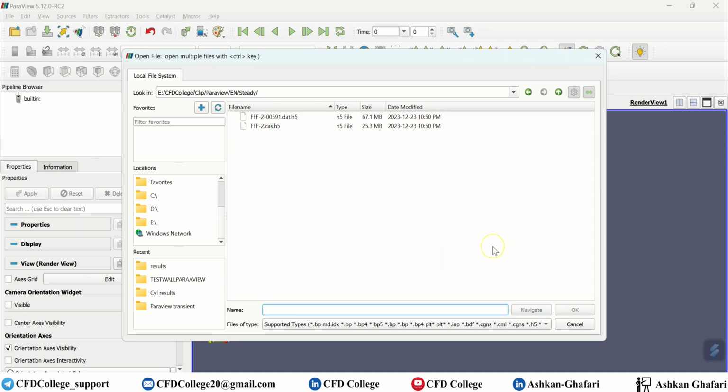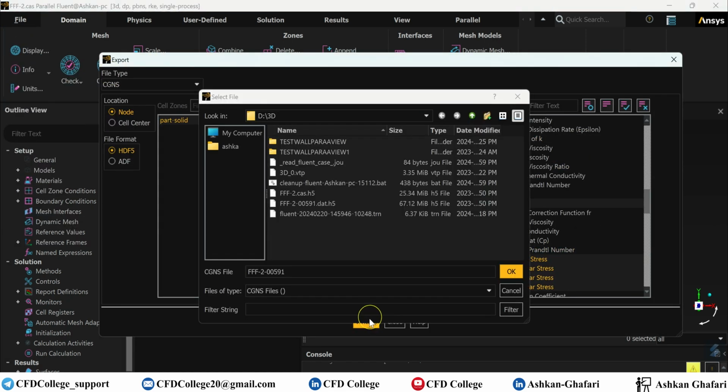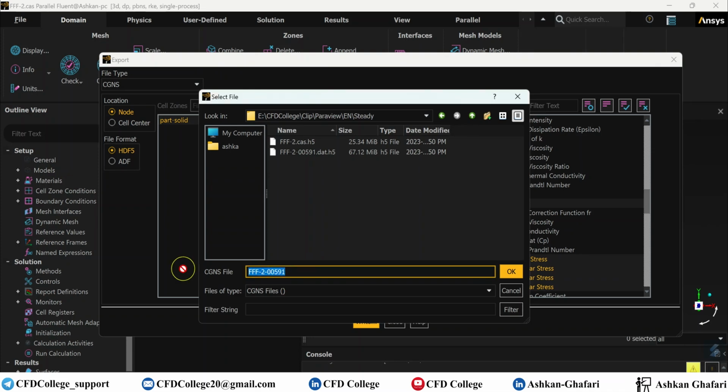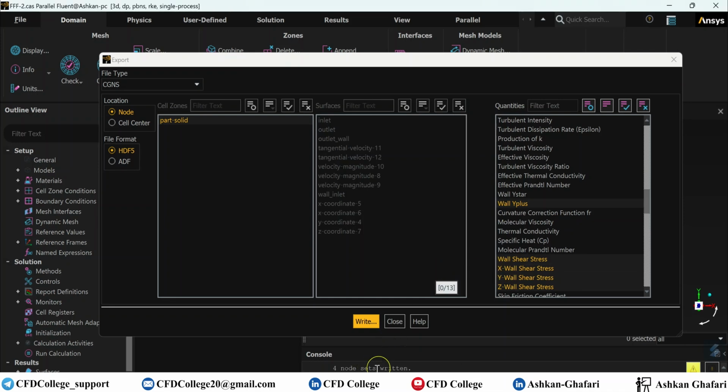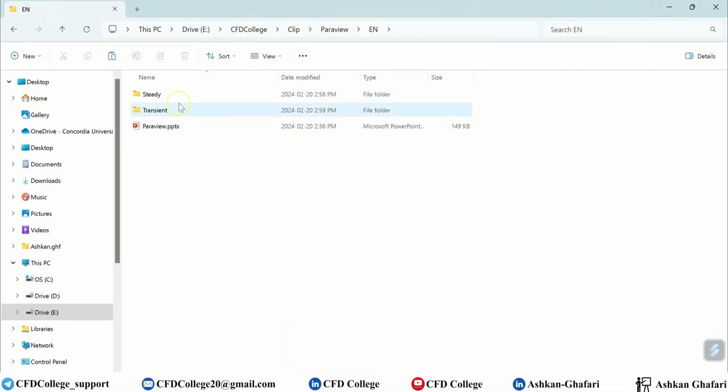This is the steady state results that I exported using the mentioned method. Actually, I should copy and I think export them. These are fine. And let me once again go to the mentioned directory here. So I specify a name, steady results, for my file, and by clicking on OK, you can see here different parameters are now done. Parameters are written. Let me go to the directory. Now you can see here we have steady result.cgns.